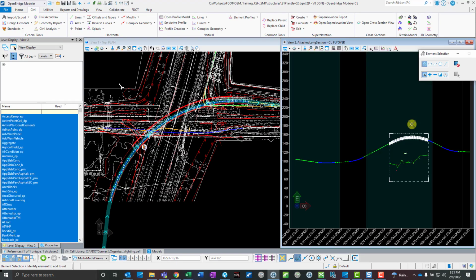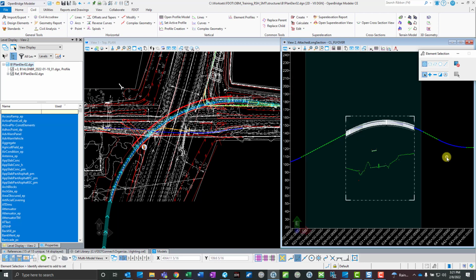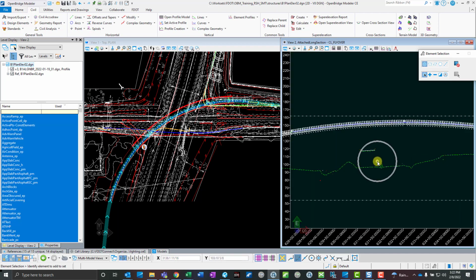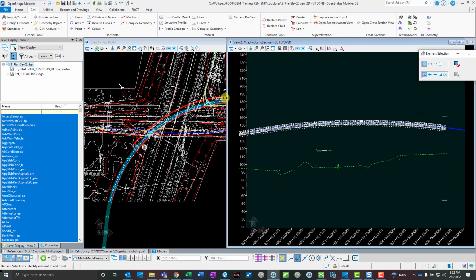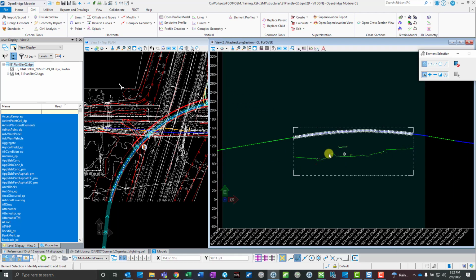And it might be grabbing some other stuff like the survey files, the motif file, but if that happens, then we can go ahead and just turn that stuff off. So I do see that in there, got the terrain, and it's going to have some aspect ratios, kind of a vertical exaggeration. I can hold the control button and middle mouse wheel to make that a little bit flatter, more normal to what I'm needing here.